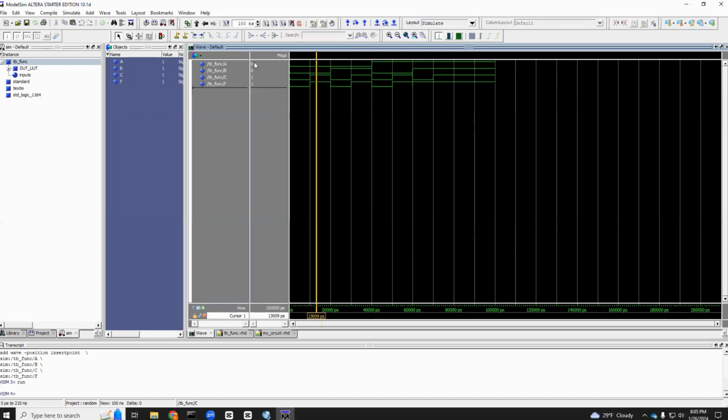Now, one of your inputs went to 1, so 0, 0, 1, 0, 1, 0, 0, 1, 1, 1, 0, 0, 1, 0, 1, 1, 1, 0, and 1, 1, 1. See how convenient it is to search for inputs and outputs. You can just verify sequentially. Whereas in the other case, you had to look for different combinations like 000 or 001. It used to be very problematic. So a test bench is a very neat way of doing it. And in the industry, they always use test benches. So this is something that you need to get used to as well.